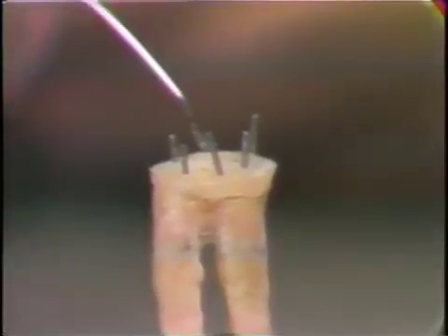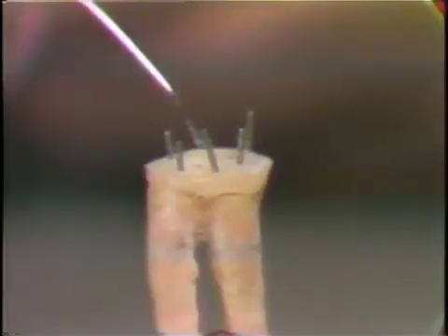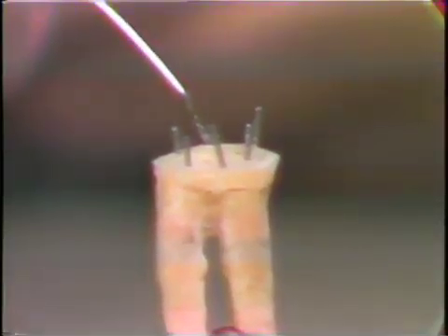That's been done deliberately. Now, these pins can be either cemented in position into an oversized hole. Some pins are made which screw into position. These particular ones are friction grip pins. And an undersized hole, about 1/1000th of an inch smaller in diameter than the pin, is drilled with a small twist drill. These pins are then pushed into position. They have annular barbs running round them, a very small dimension, which prevents them from coming out once they're pushed